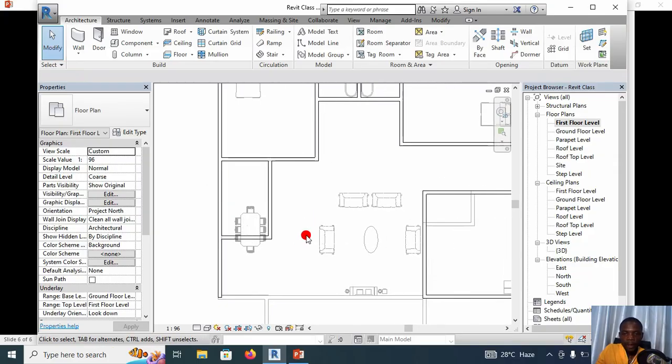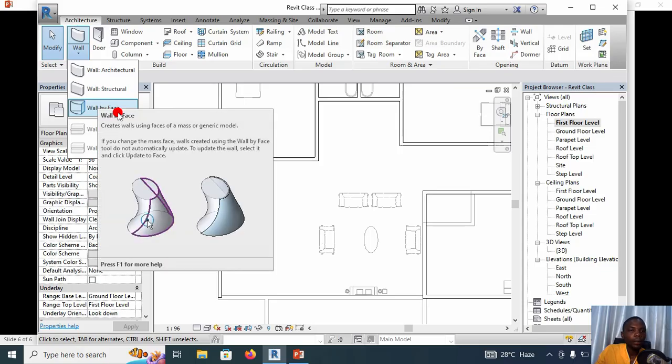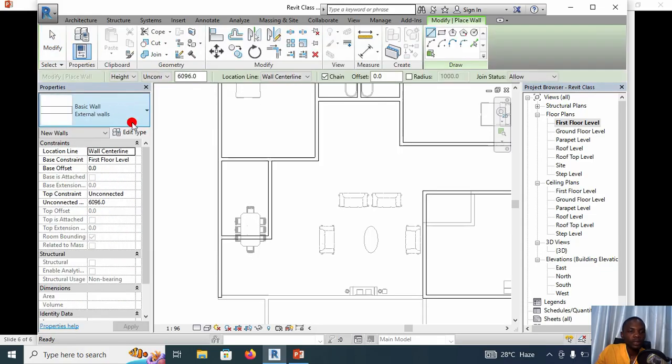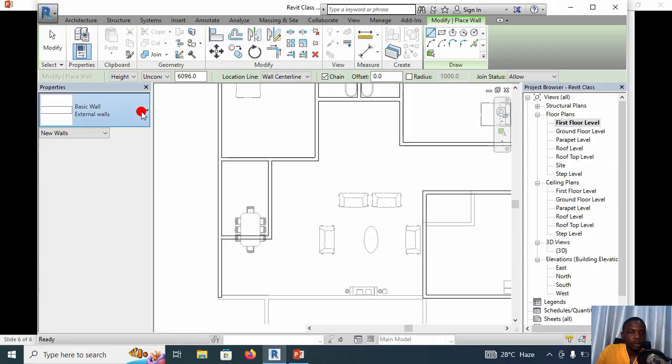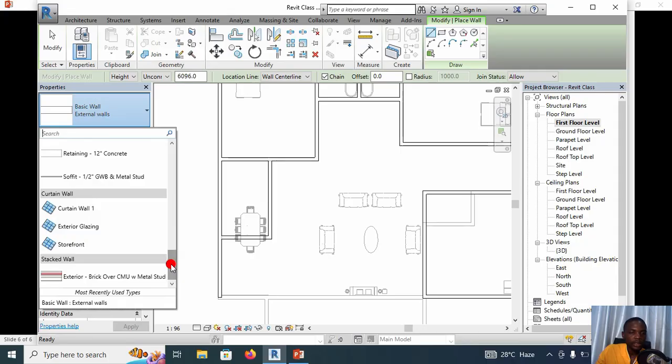So now I want to have a glass wall here, right? So that this place will be a kind of a lounge, right? A kind of an open terrace, so to say. Let's call it an open terrace, right? So how do I do a glass wall? I'll go under wall, right? Architectural wall, of course, and come to this place, scroll down, right? You can see storefronts, right?